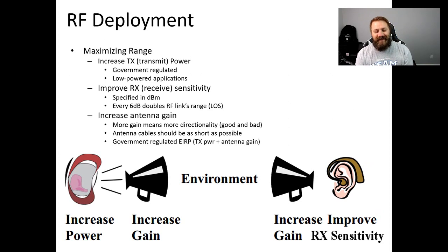But we can also increase antenna gain. So more gain means more directional. That can be good and bad. It depends on what you're working with. Sometimes you want a broad antenna, which makes it easier for the technician to aim. It receives a little bit better.